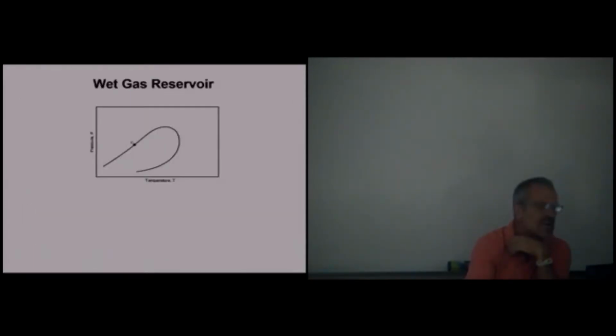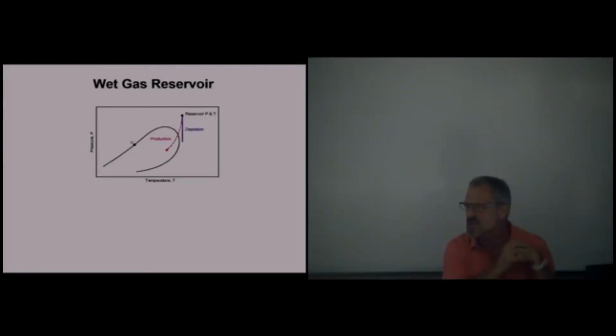And then about gas reservoir. By and large, when I'm talking about the general case, this is what I'm talking about: a reservoir that is a gas reservoir throughout the life of the reservoir. I do this because it's the easiest case. If I actually have a condensate reservoir and my whole reservoir generates a liquid saturation, it changes the physics of my flow model, because I now have two-phase flow in the reservoir rather than single-phase flow. So I like to stick to this case as the more general case.